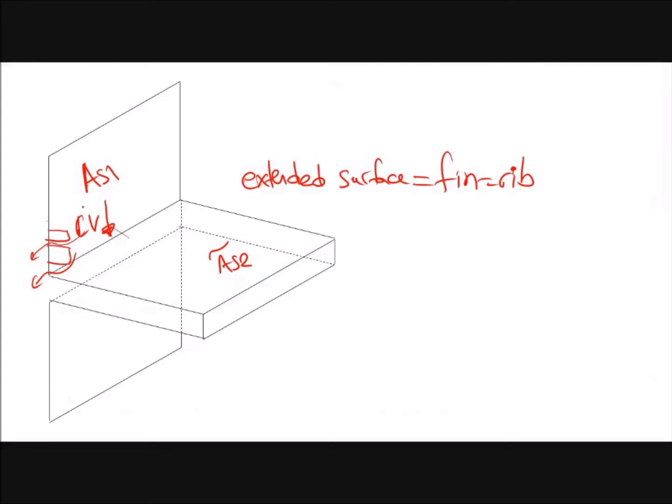If convection heat transfer drops, then adding fins doesn't bring any advantage. It is very similar to having a line with clothes on it. If these clothes are very close to each other and the distance is very small, it means that air cannot enter between the clothes and they will always be wet.